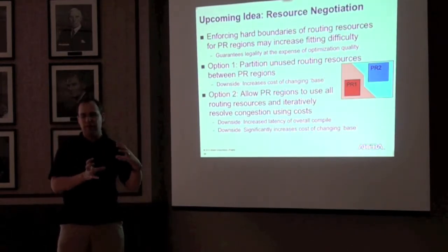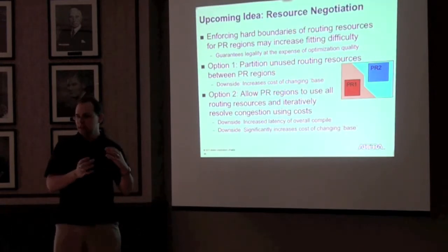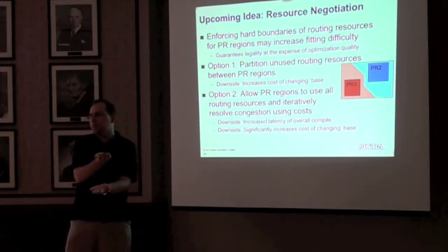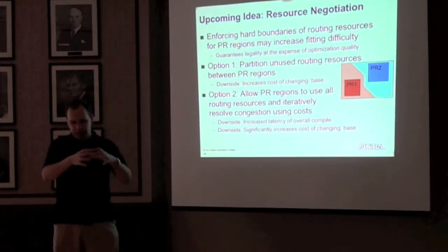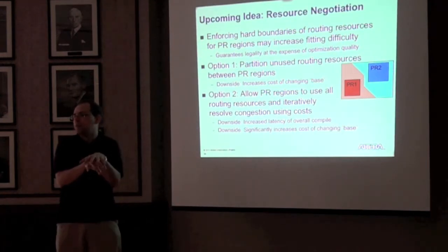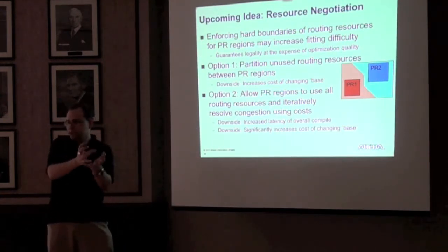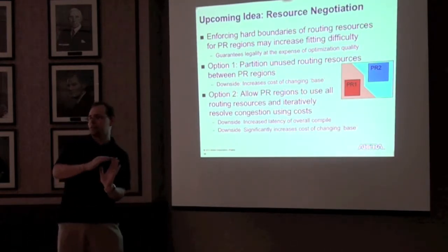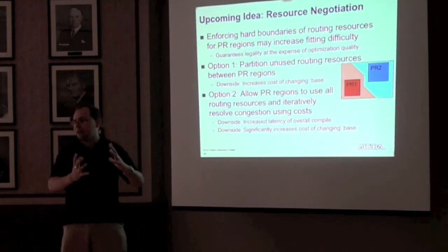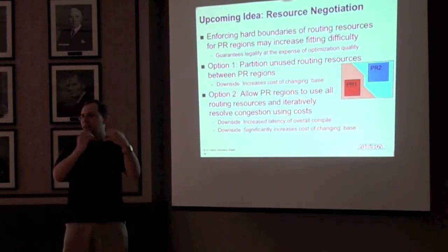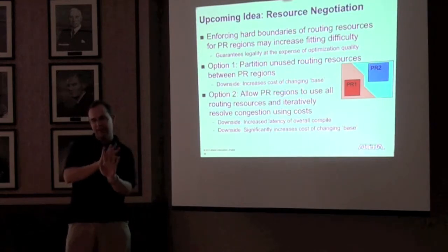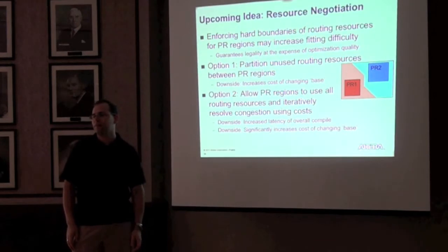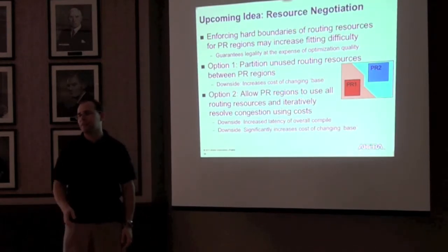However, what you define as the PR regions and the personas essentially defines what the chip can PR, right? So you want to combine two together into one PR region, that's great, right? Full optimization, complicated resource sharing, synthesis, placement, everything is going to be optimized. But you're not going to be able to say, oh, now bring one in and not the other, because all of those steps of adding the anchor LUTs and really defining boundaries and getting those partial bit streams, it's not about combining and then the tool can just separate it out at will. Hopefully that answers your question a little bit.